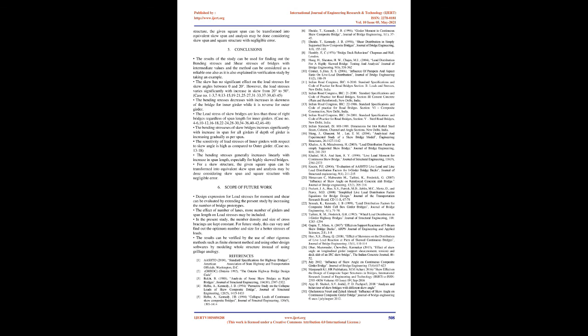6. Scope of future work. Design expressions for load stresses for moment and shear can be evaluated by extending the present study by increasing the number of bridge prototypes. The effect of number of lanes, more number of girders, and span length on load stresses may be included. In the present study, the number, density, and size of cross bracings are kept constant. For future study, this can vary to find out the optimum number and size for better stresses of loads. The results can be verified by the use of other rigorous methods such as the finite element method and using other design software by modeling the whole structure instead of using grillage analogy.